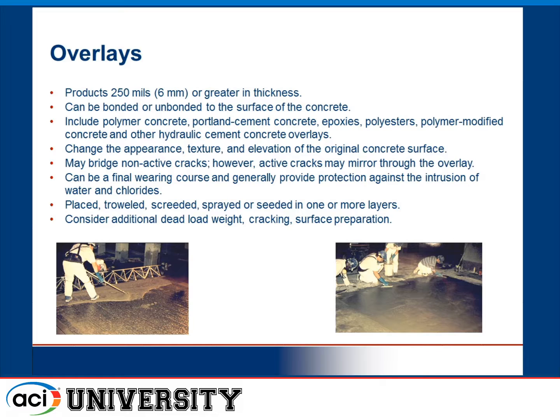Other considerations that need to be taken into account are the dead load weight and the possibility of cracking when these are allowed to dry too quickly. They need to be cured. They need to be treated as regular repair. But surface preparation is critical. If cracking is expected, if movement is expected, many times that would make you choose an unbonded overlay